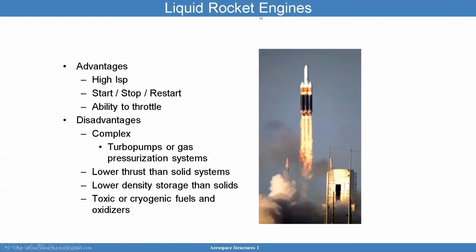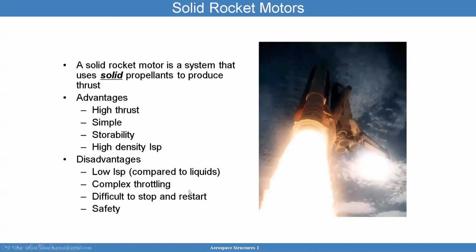So liquid rocket engines, again, advantages: high ISP, ability to start, stop, restart, and throttle. Disadvantages: complex, use turbo pumps or gas, lower thrust than solid systems, lower density storage than solids. A solid rocket motor is essentially a bazooka that has high density. The disadvantage of liquid rocket engines is that the propellants are toxic and we use cryogenic fuels and oxidizers.